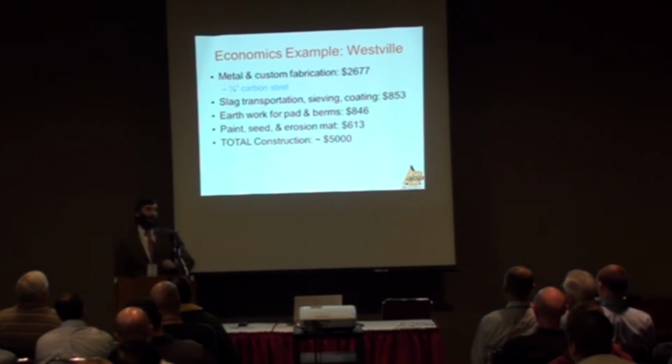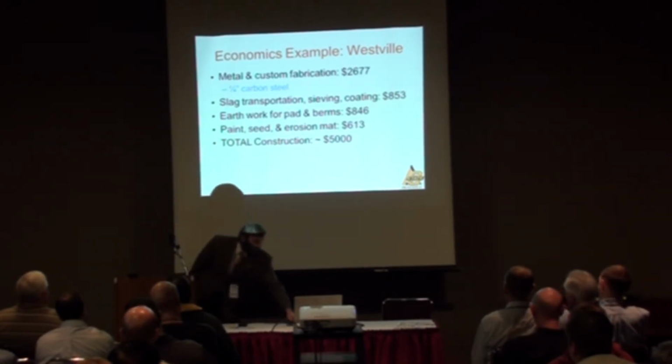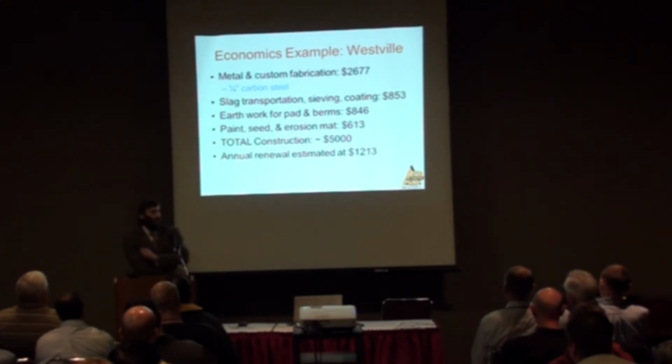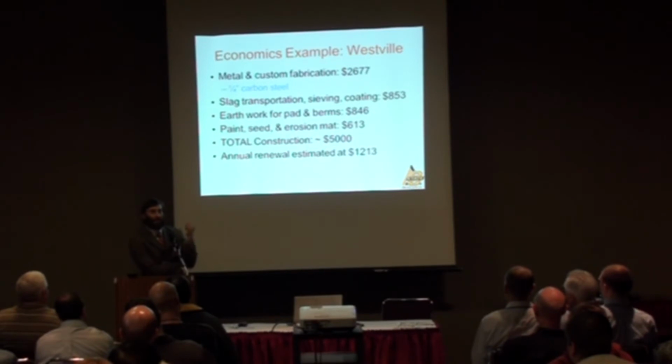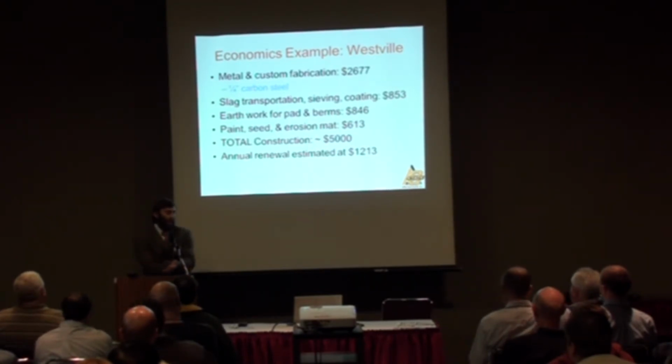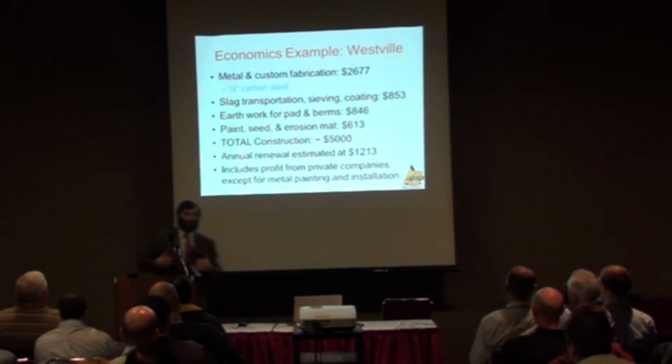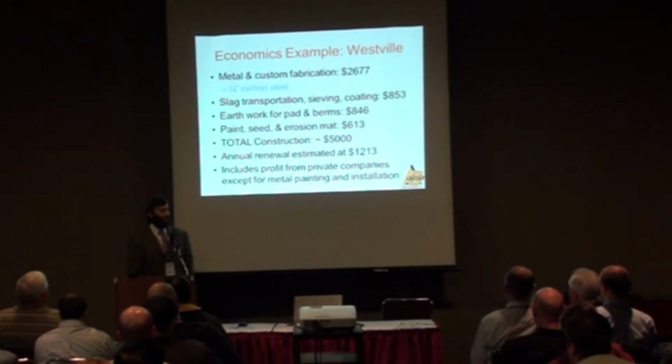Total construction cost is about $5,000 for that filter. I've estimated annual renewal, although it's going to be longer than annual since it's performing better than we had expected. Annual renewal estimate, including profit by a private company, around $1,200. That's for disposal, clean the material out, and put new fresh material into it.